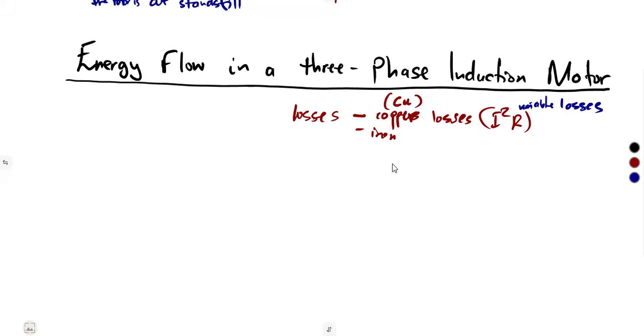All right, so we've got the copper losses, then we've got the iron losses also in your calculation. So the iron losses, remember, these occur in the what? In the iron parts of the motor, where we've got the eddy current losses and the hysteresis losses. Those build up the iron losses. So we have got what?